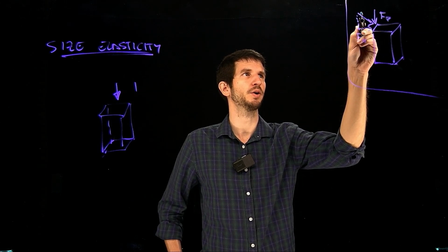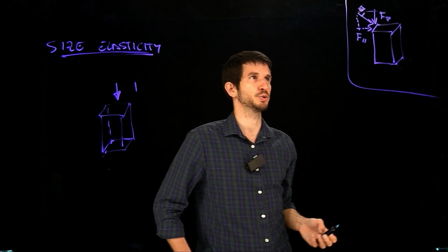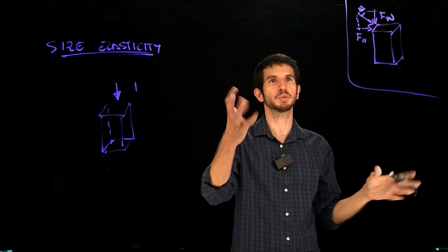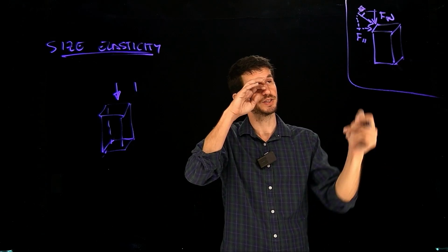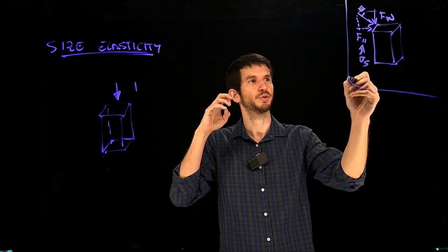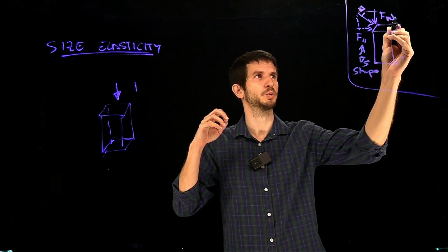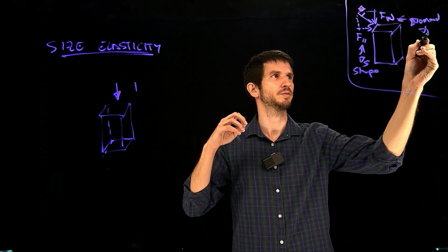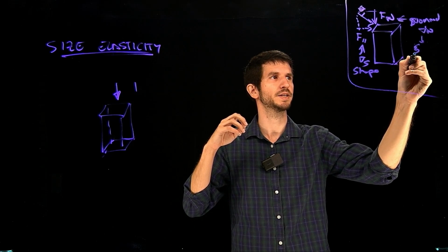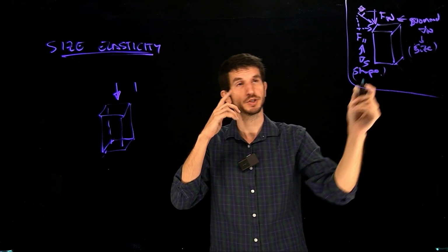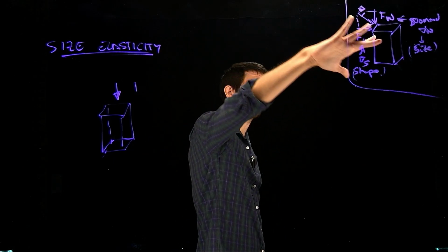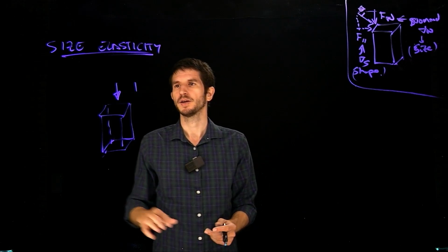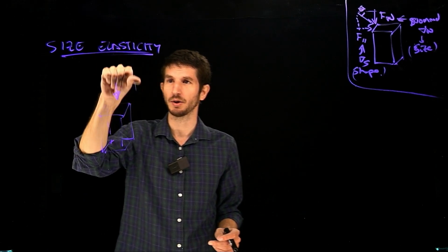And so depending on the angle in which I'm applying that force, I'm going to use SOHCAHTOA to say how much is the normal force component, how much is the parallel, and I split it into two. This is going to be responsible for shear, which is the deformation in shape, and this is going to be responsible for normal stress, which is sigma n, and it's going to be responsible for size change. Okay, this is shape, this is shape. So that perpendicular force is going to deform the shape, but also compress it, for instance, right? And the same thing we could do if we were pulling. But anyway, let's assume we're just pushing down.